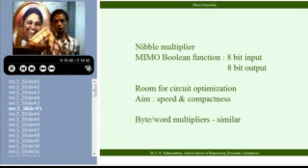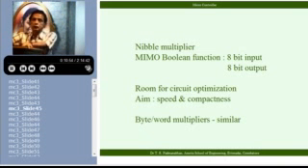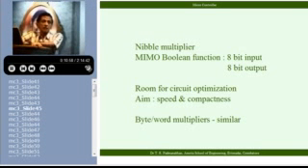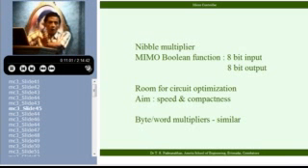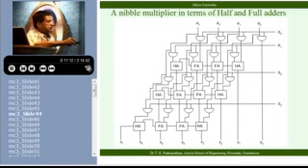What you can do is prepare the full table of input-output relationships and, using 2-level logic gates as we discussed yesterday, make an elaborate circuit and realize it. If you do that, it will be a well-optimized circuit. So many gates will not come into the picture, so much delay will not come into the picture. For example, in this circuit, if A0 changes from 0 to 1 or 1 to 0, the change has to propagate through all of this, and finally it has to appear as a change in S7.